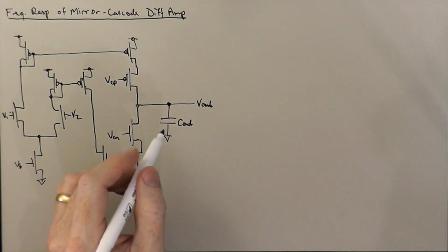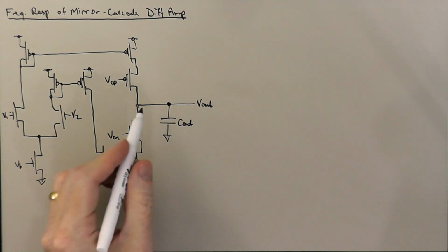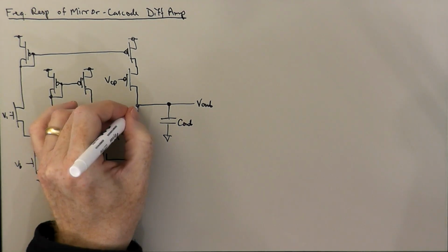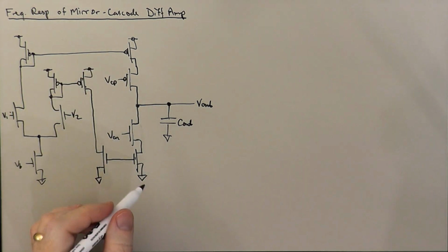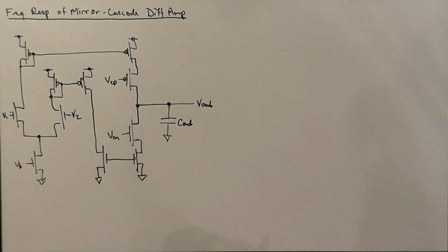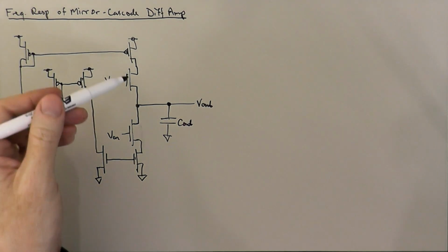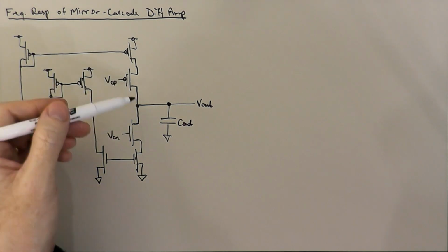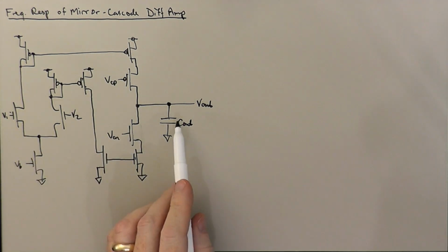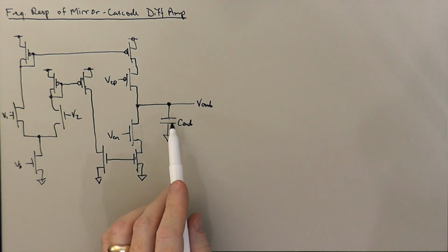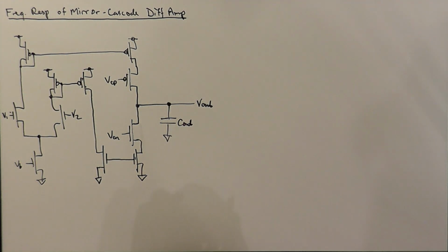Right? So we could imagine splitting the output into two pieces, one connected to the output branch of the amplifier like we had before, and the second branch being that capacitor all by itself. And we would find the original incremental output resistance of the amplifier that we calculated last time, and then we'd have the 1 over j omega C out in parallel with it.